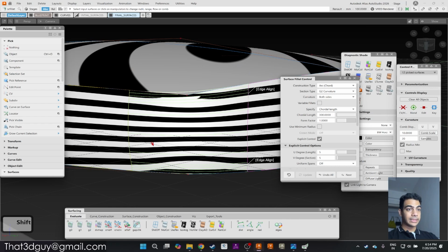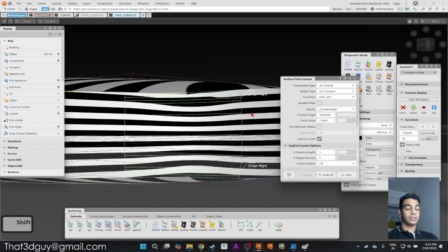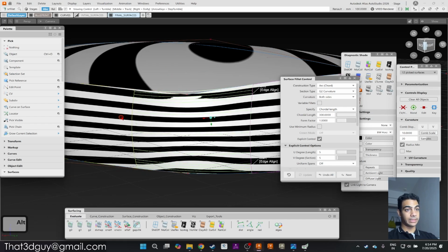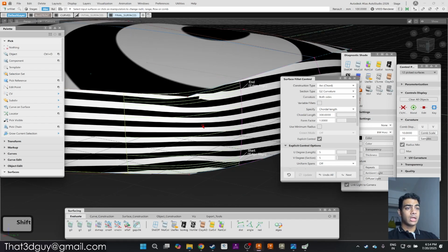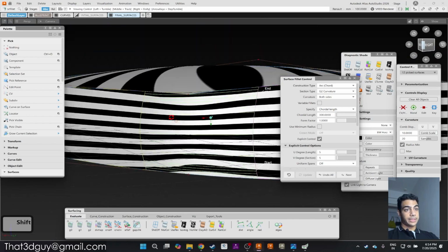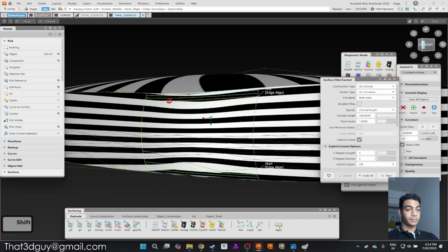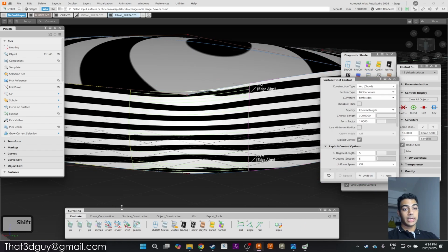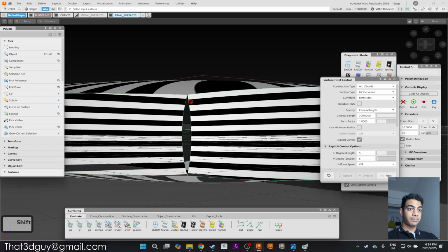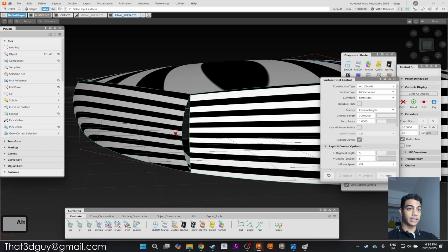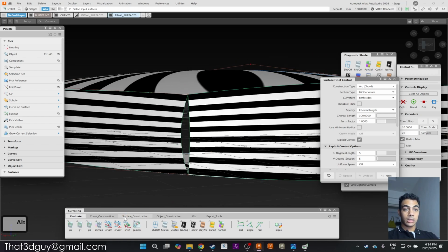We could obviously try to trim these and then again fillet between them manually using freeform blend or any other tool. Yeah, so sometimes filleting works, like the normal surface fillet works. The software is able to recognize the edges. It could also be due to a gap here. So as you can see, there is no positional continuity over here, because of which it is basically breaking and causing this issue. Now we could obviously project the curve and then trim it and then freeform blend it.